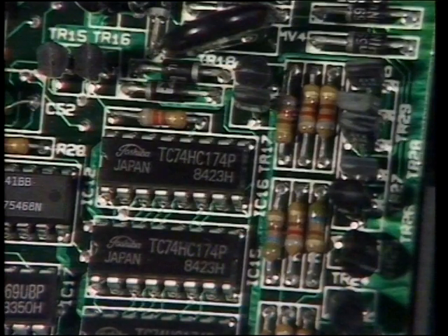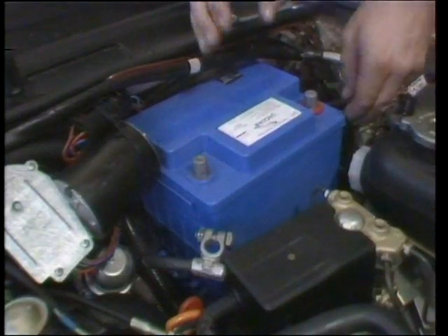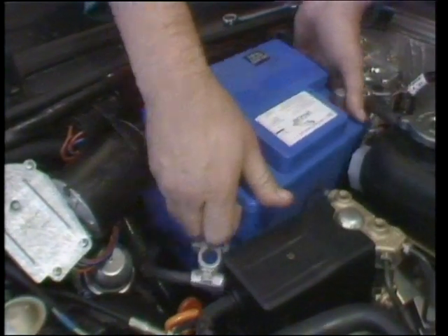All ground connections on microprocessors and logic circuits are taken to a wire which is connected to the battery earth. This minimizes any voltage changes on the ground connections of sensitive electronic circuits. This is called the logic earth and is located on the bulkhead at the closest point to the battery negative cable. All logic earth cables are colored black and pink.